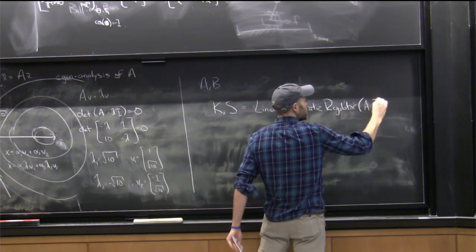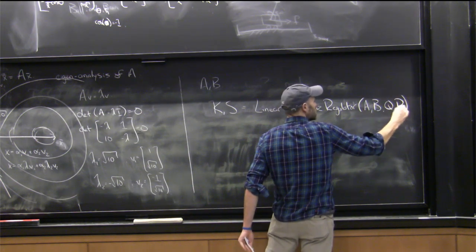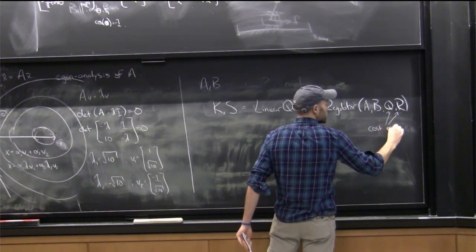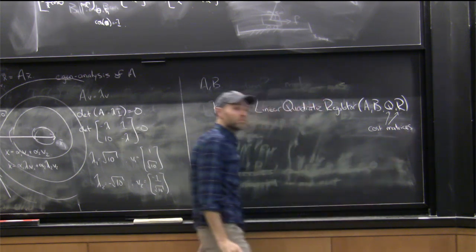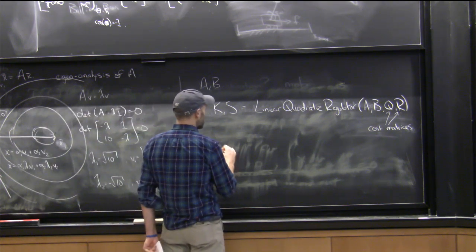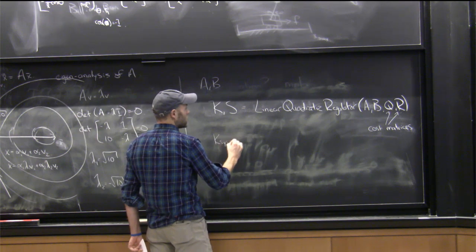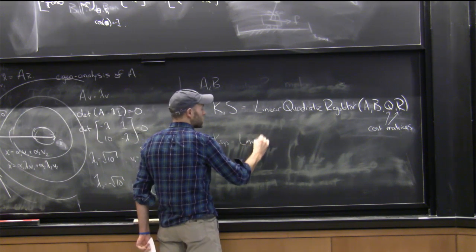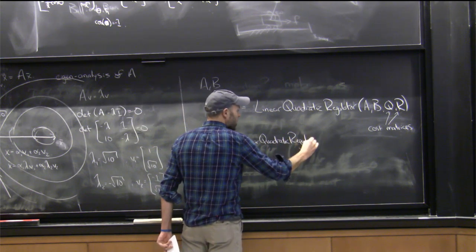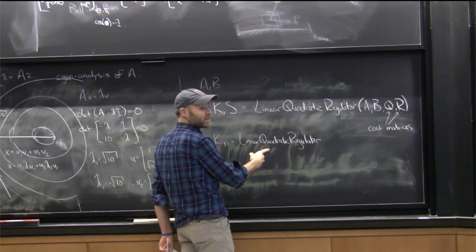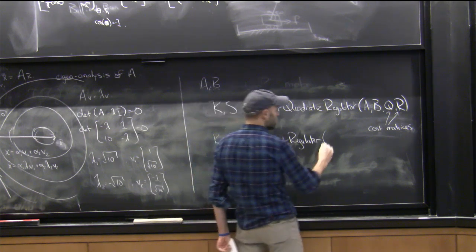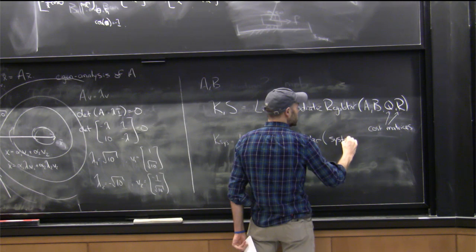And you have to pass in A, B, Q, and R, which is my cost function, right? You can also just call it this way. Since there's nothing hidden, calling a linear quadratic design principle algorithm against the nonlinear system implies that you're going to take a linearization. So we can also just pass in the system.